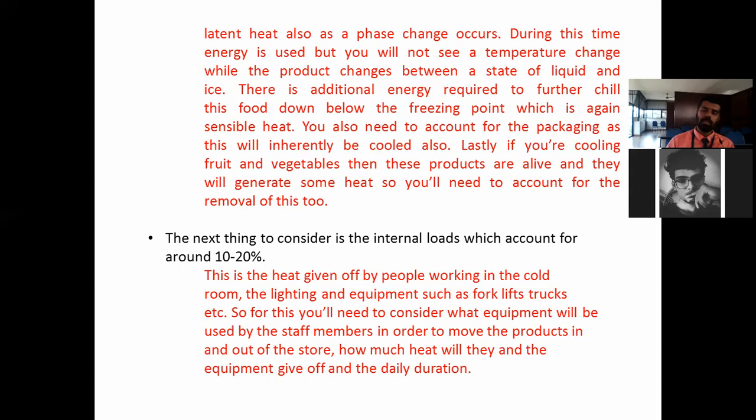So if you need to find out a cooling, you need to find out only sensible. Then if you want to freeze it, you have to calculate the latent heat also, because the phase is changed. Further, if you continue to freeze, we still need only sensible heat, because the phase is not changing. It is staying in ice form.